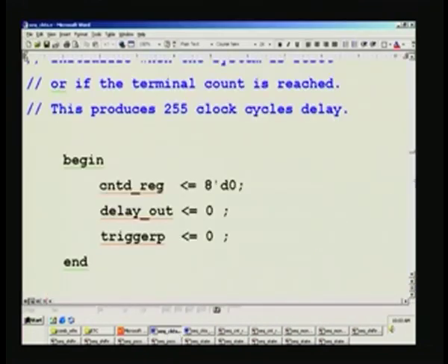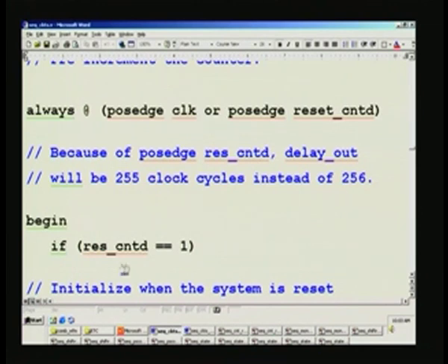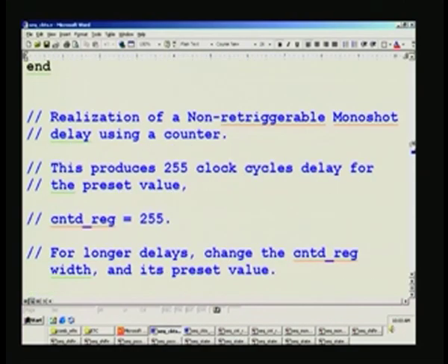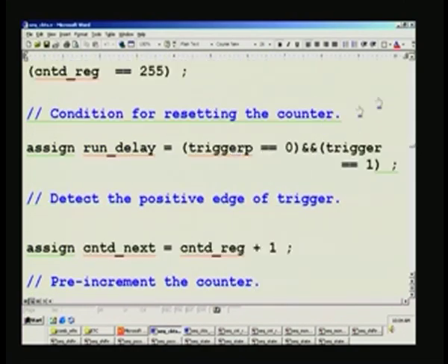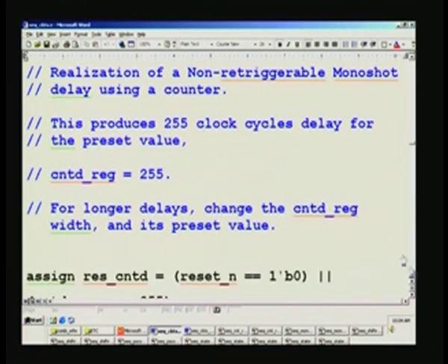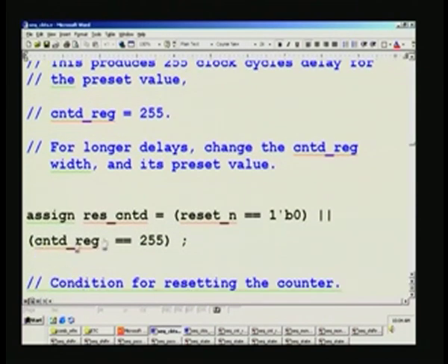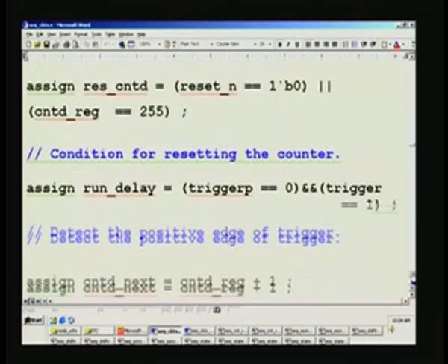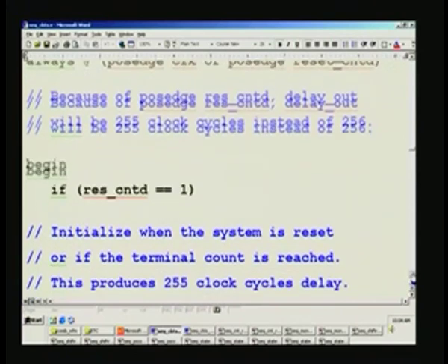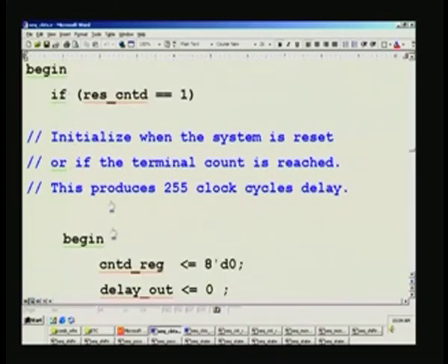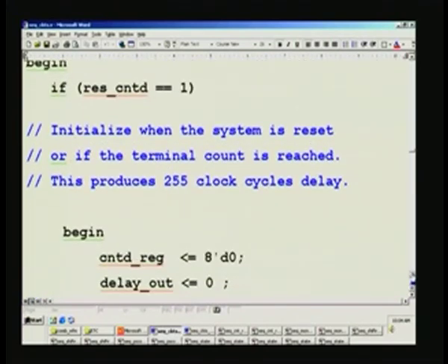Actually it was here. See, here we are saying reset, and this is for combining the power on reset as well as the counter reaching 255. Earlier I did not combine this. Why I combined it here is that I have also said always block is a priority encoder, therefore we have to limit the number of ifs and else ifs to less than 4 or 5.